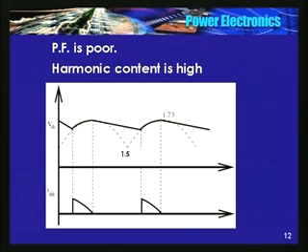Okay, and at steady state, that's how the capacitor voltage will change. Okay, so this is of 60-degree duration, and each device can conduct for 120 degrees in a three-phase full bridge. Okay, so D1, the diode which is connected to phase A, conducts for a very short duration.